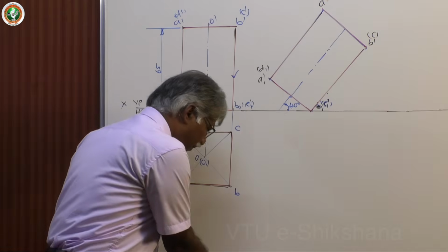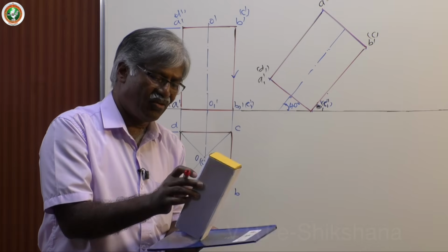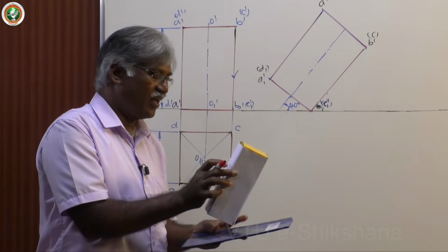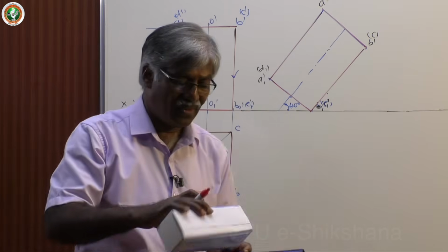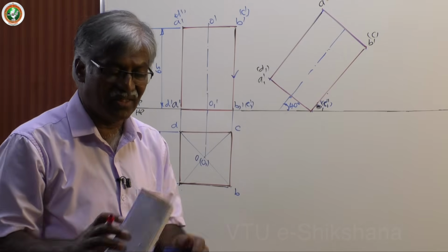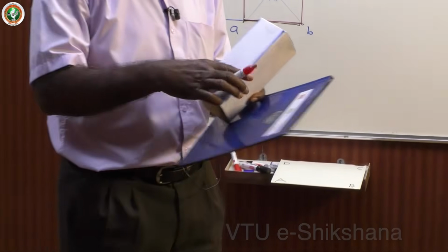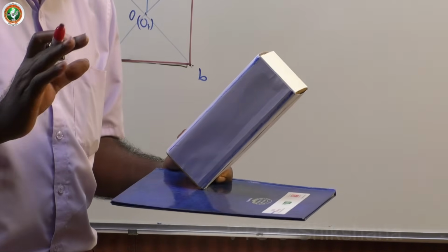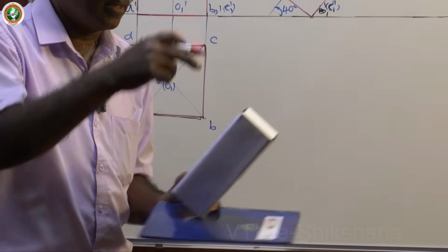That means we have given inclination to the solid with one of the base edges on HP, axis inclined some degree to HP, 40 degree. Now we have to get the corresponding top view in this position. In this position, I have two colors, key surfaces I can say. One is the base surface and the other the top face. Top face is light color and this is dark color. If I keep it like this and rotate, as usual, the lateral surfaces are white. In top view, you cannot see the dark color base. You can see only the light.